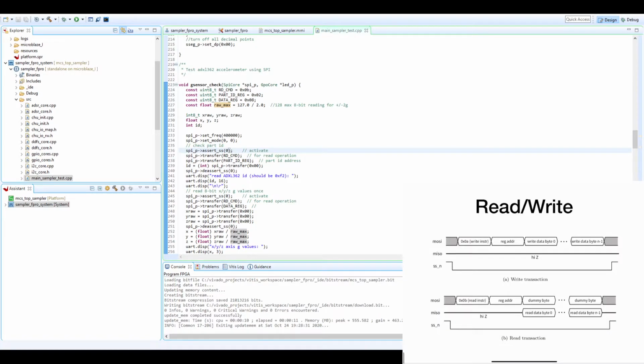The graph tells you that if you want to read, what you need to do is send the read command. And we know that the read command is this one here. So we are reading. So the one we're actually after is this one here. So the read command, we stored it in here, and it's basically 0B. We just send it, and then the next thing we do is we send the register that we're interested in, and that's register number 2.